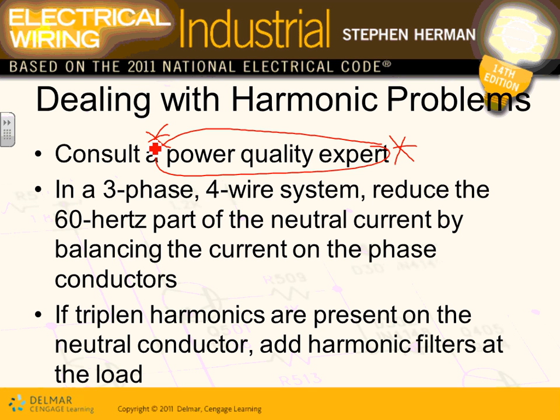If you don't know how to interpret it, you're going to give it to a power expert, and they will tell you, yep, based on these readings that we got, you have a problem with the fifth harmonic, and we're going to plug in a filter for you to cancel the fifth harmonic. So there are filters that they can add to the power system, guys, that can get rid of them if they're that severe. If they're not that severe, you can live with them by oversizing your equipment. Did you guys hear me? Either you oversize your equipment or you solve the problem by filters.